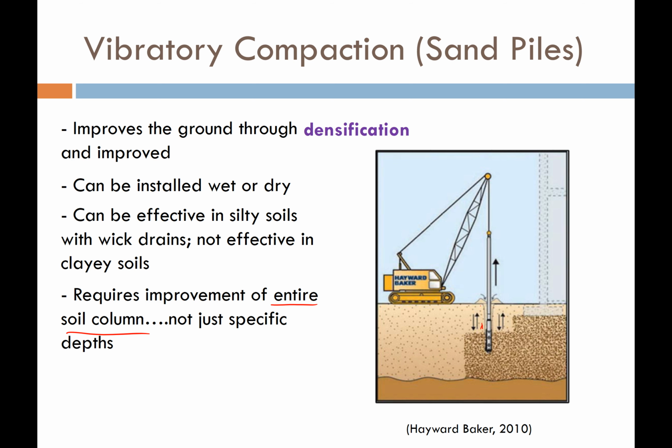So the way that this method works is we're going to improve the ground by densifying the soil, increasing the relative density. And it's also going to improve the drainage of the soil because we're adding clean sand to the soil, which increases its ability to drain water out.